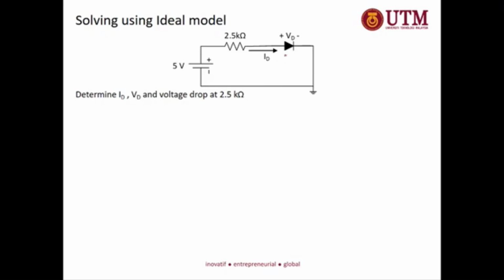Okay, let's see here. This is positive voltage. The positive voltage is connected to the positive terminal, the anode. And then the negative is connected to the ground. So the anode has a higher voltage than the cathode, which means this is forward bias.